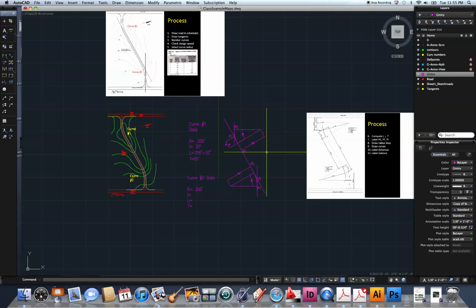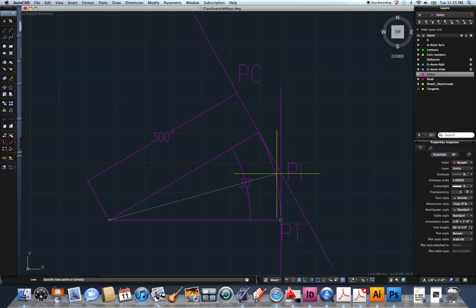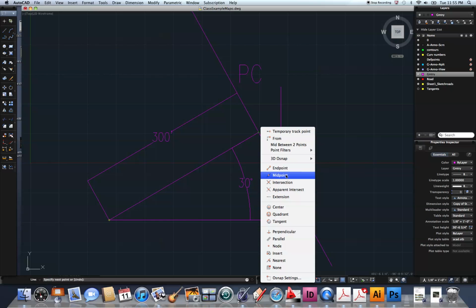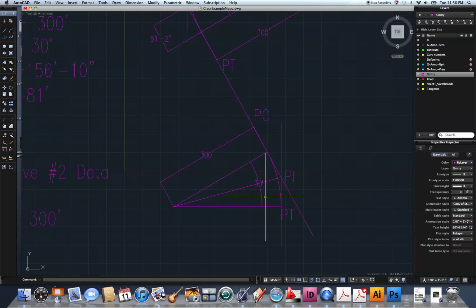If you were doing this by hand, well, actually in this case we can draw in a radius line, so I'll go back over here to drafting while that's thinking. So we could select our line tool, or we could do L for line. And the problem is that it wants to snap to the ends of these arcs. So I want it to snap to a midpoint, so I'm going to hold down Shift and right click and select midpoint on this list. And now it snaps to the midpoint right there, which is what we want.